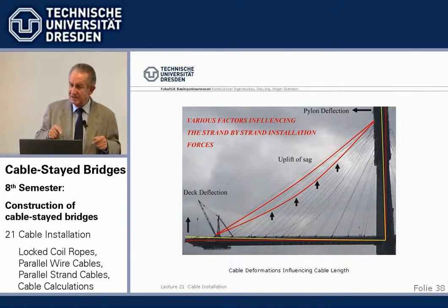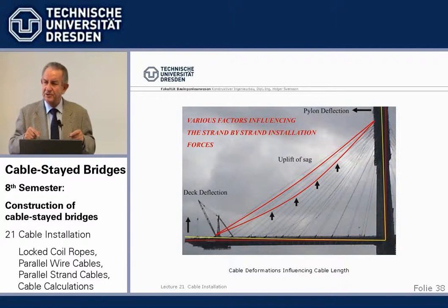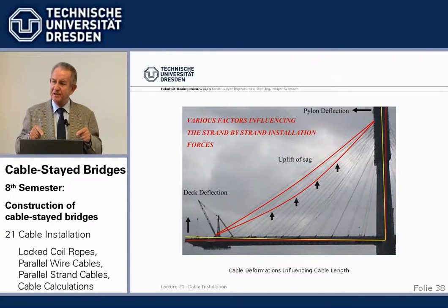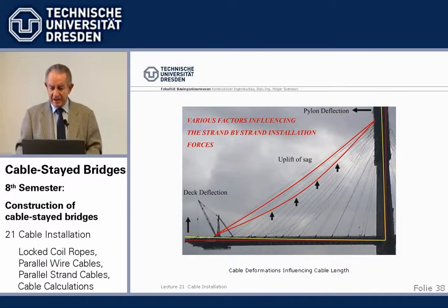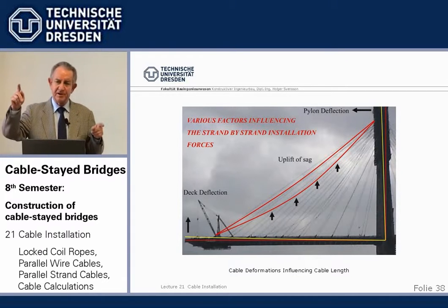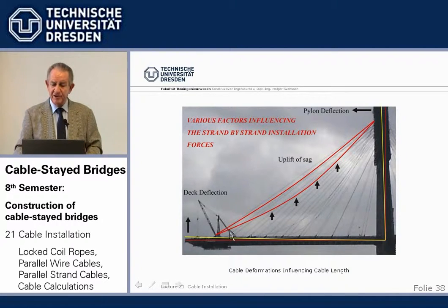Now here we do not have a predetermined cable length with site fabricated ones, but we have long strands which we cut off one after another and reinstall. And so there we have to calculate the force, not installation by geometry as with the shop fabricated, but installation by force. So we have to calculate carefully for this given situation what force these strands must have.